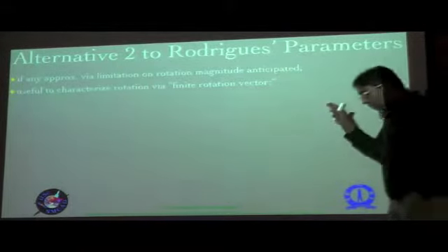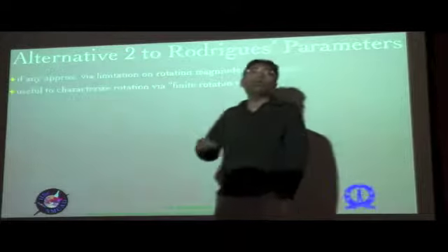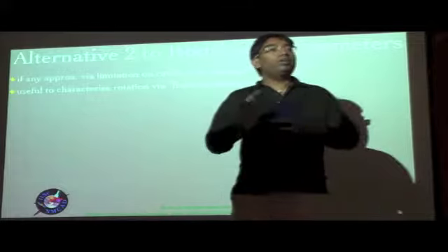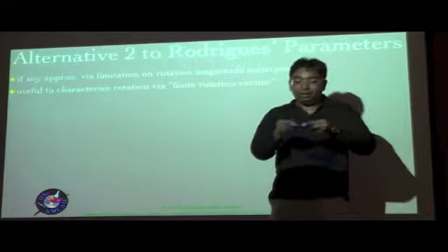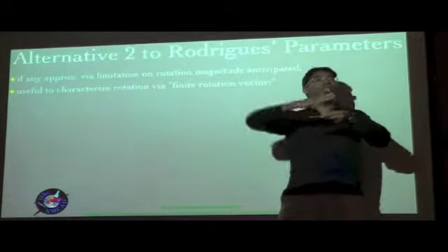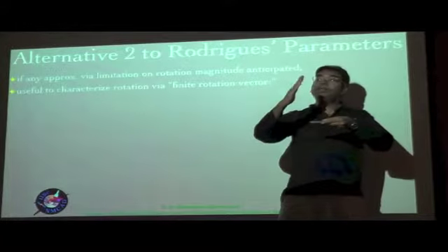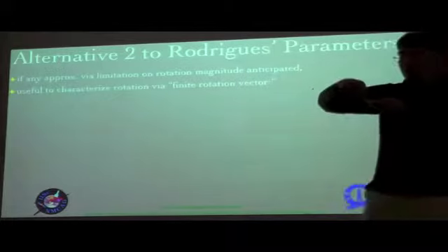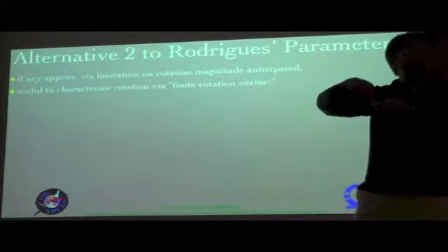Again, this is something we can use, for example, for local rotations. See, our rotation that we are going to be talking about is made out of two parts. One is basically the overall average rotations of the cross section, and then there is warping, and that warping consists of tiny line elements having small rotations.